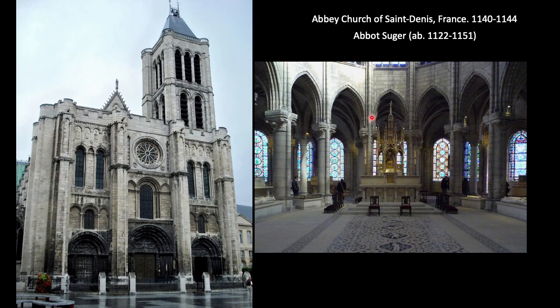However, by adding a point to the arch, the weight of the building is channeled outward and downward along a steeper angle and therefore at a greater rate, while the sharp apex of this point also has a strong upward visual emphasis. Because the stress is channeled at a greater rate, pointed arches and vaults in general can be taller and span greater distances than their rounded counterparts.